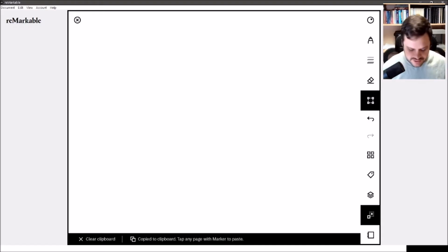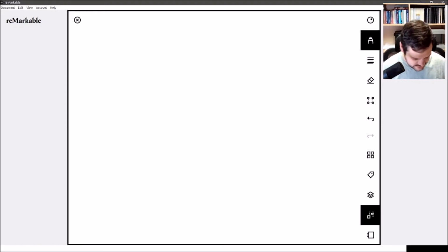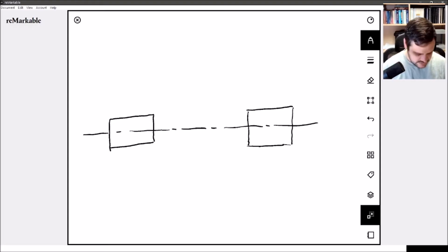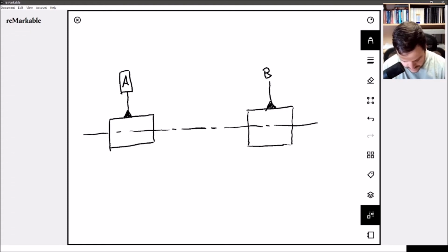Okay, so now I'm going to draw an over-exaggerated version of this shaft. If we consider our two end sections, something along these lines through here, and then we put our common center line through the guts of all of it. The way that we draw that onto a drawing is we have our little triangular section with datum A, and then we have our little section through there with datum B.